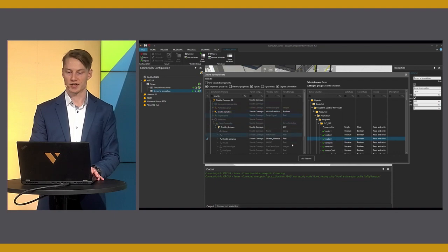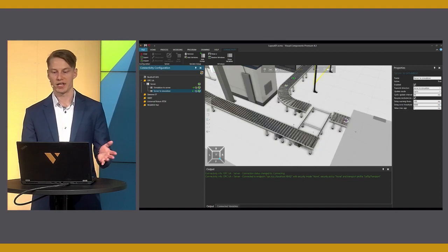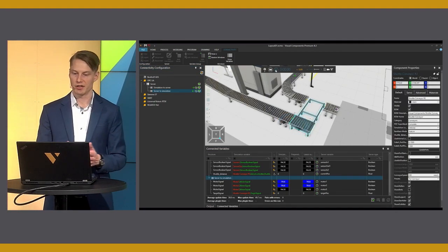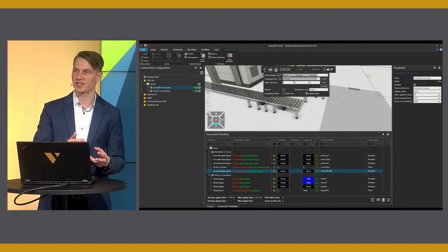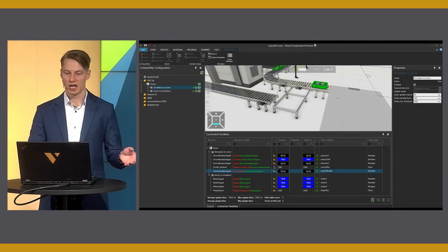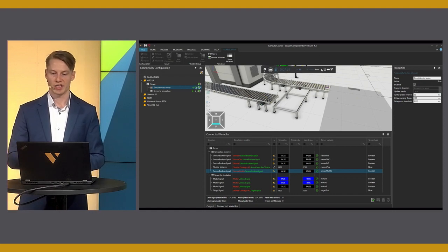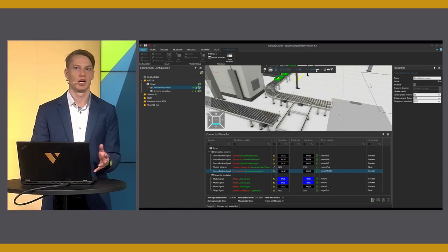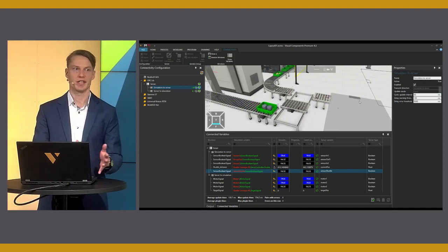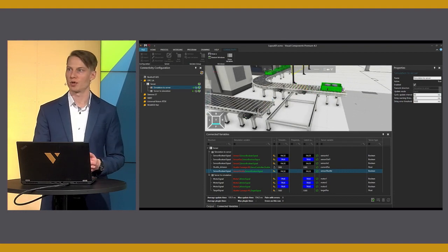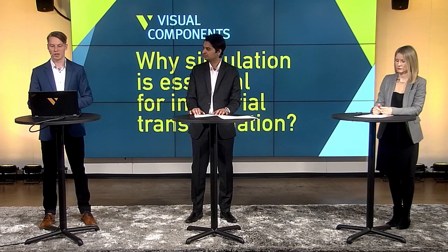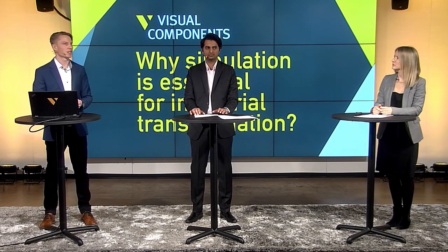The signals and servo values are connected to the PLC by mapping them. This can also be done by importing the config as an XML file. After mapping, we run the simulation with a good warm-up time until the point we are interested in, and run the simulation with the real-time speed factor 1 and see how it goes.